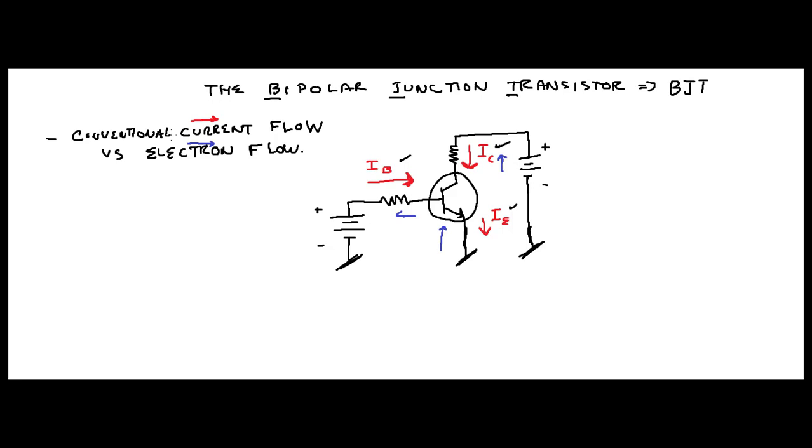So what I just showed you, I showed you electrons coming up from the emitter towards the device right here, all right? Up here, coming on in, and then I showed you a small percentage of them come out of the base, and the rest of them, 91 to 95%, continue on into the collector, okay? So I kind of made that arrow a little fat, sorry about that. I'll redraw that one for you. So they come right up here this way, all right?